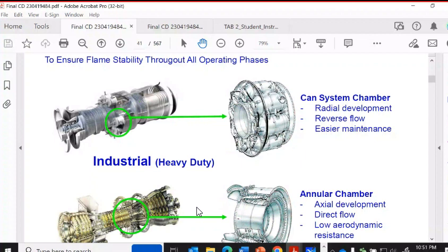But the problem you have here is these have a short operating life. They're about 10,000, a little bit more hours, depending if you're running liquid fuel or gas fuel. But you usually get premature structural cracks on the support pieces and where it's anchored. And like I said, it's a big void. Should one of these give you a problem, I get a big shift in my temperature pattern, and that will compromise the output capability of the turbine.